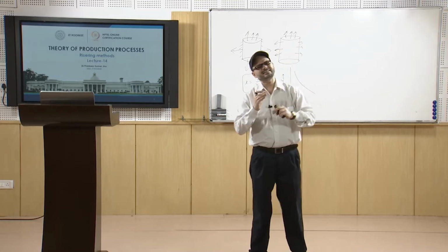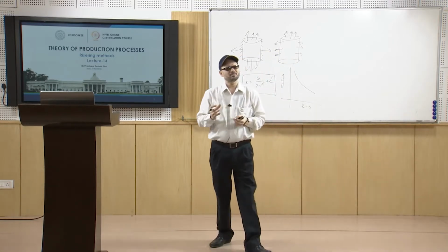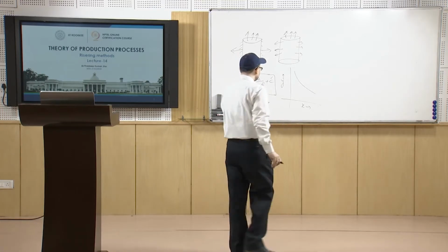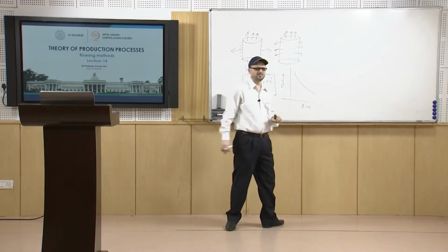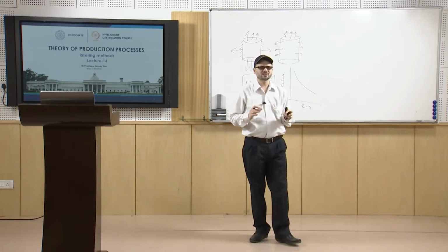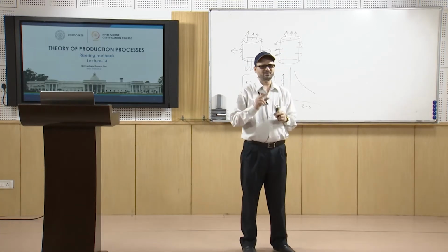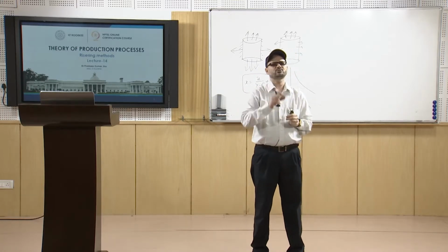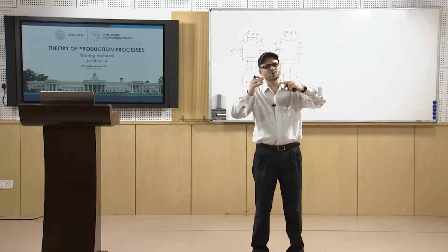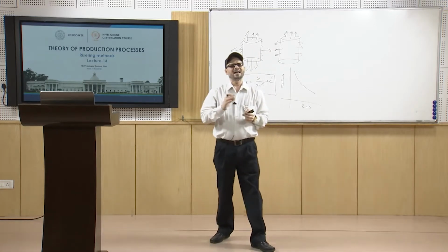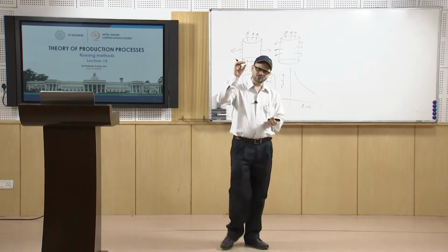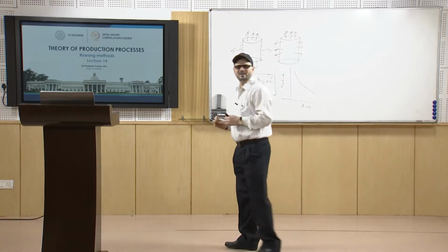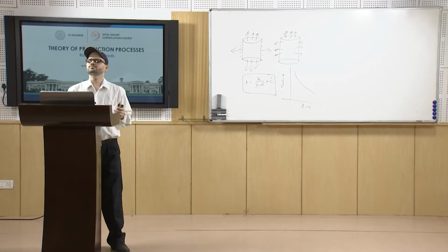Here, the freezing ratio term on the x axis is replaced with the shape factor, and shape factor is nothing but L plus W by T, that is, length plus width by thickness. Once you know the length, width and thickness of the casting, you find the value, and then you have a graph that you can use.